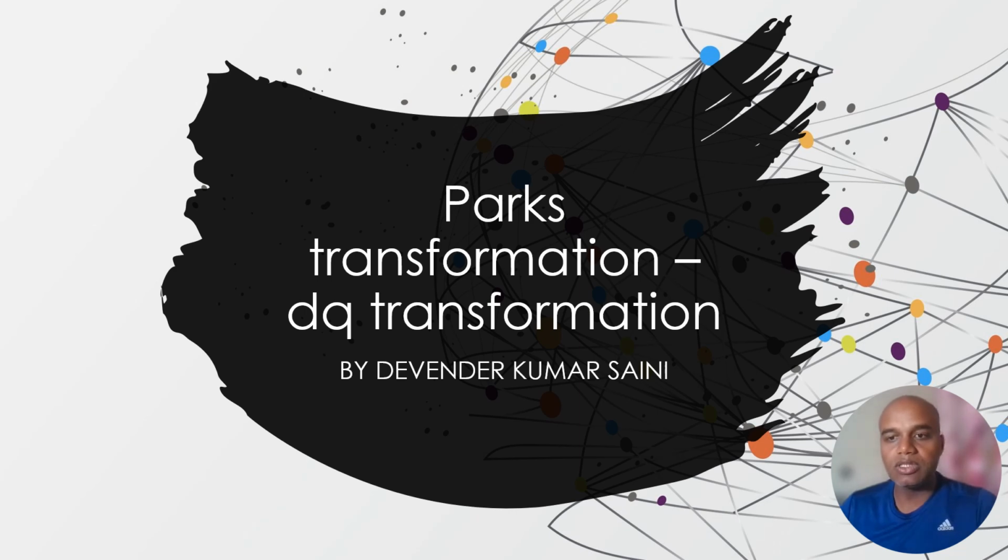And further, if we have the DC values, in other words the decoupled values in terms of the torque and the flux, which happen simultaneously in my AC machines. So once I get the decoupling, that means I can have control on torque and flux independently, just like a separately excited DC motor. So it is very simple to control those values by using the PI controller.